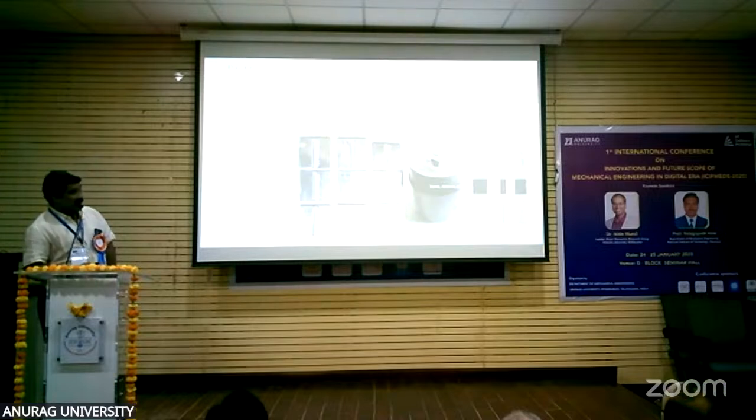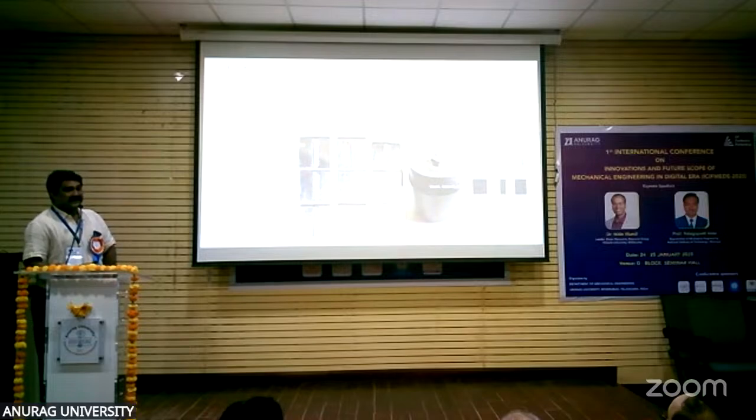For the design of the tool, the shoulder diameter is 18 mm, the pin diameter is 6 mm, and the pin depth is 4.9 mm. The base material thickness is actually 5 mm, so we take 1 mm less. Due to that, the friction stir goes well below the recrystallization temperature, and the welds get good quality.